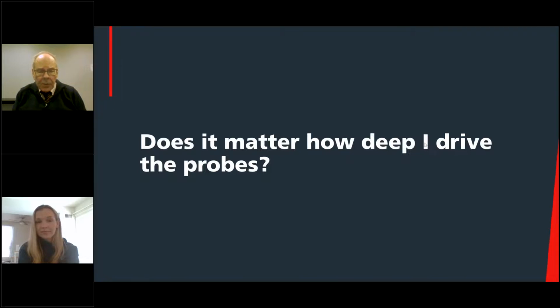So just be familiar with the indicators on your tester that will come up and tell you whether your current probe and your potential probe are in deep enough, or have too much resistance around them. But those circuits on good modern testers will tolerate thousands of ohms of resistance. So it generally isn't really a problem. So don't overdo it, and then you have an issue with your back and your knees trying to get the probe back out again. But there are extreme examples where you may still need to do that, out in a desert or something like that, but not in most environments.